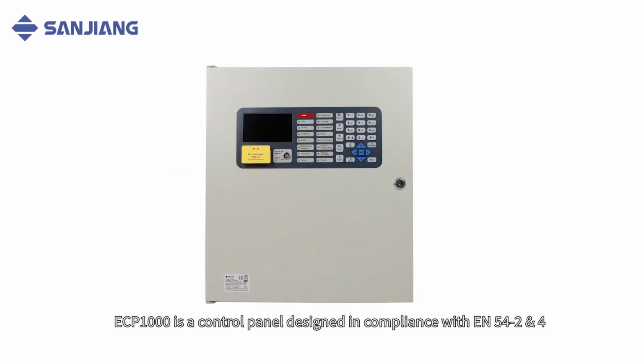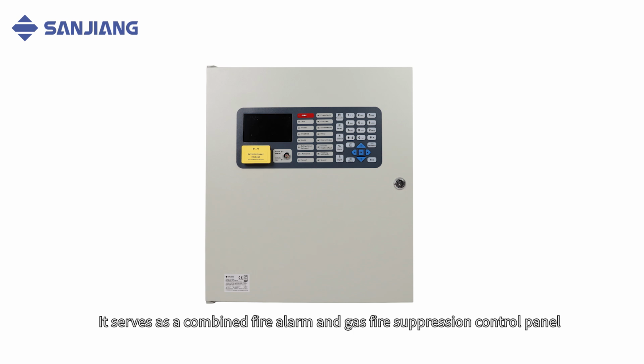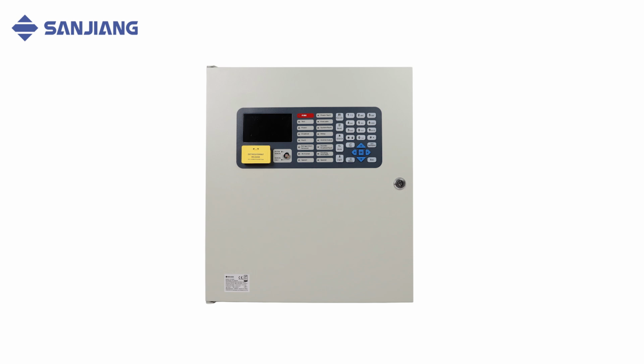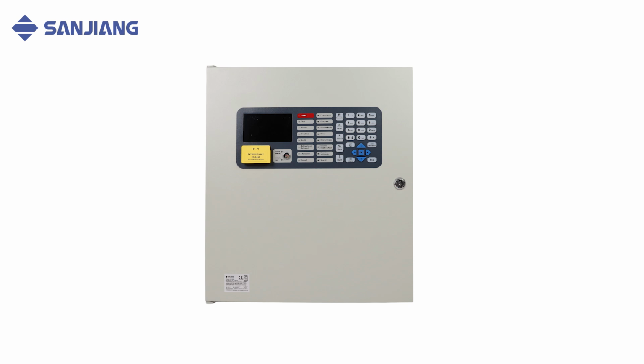ECP1000 is a control panel designed in compliance with EN 54-2 and 4, EN 12094-1 standards. It serves as a combined fire alarm and gas fire suppression control panel, utilizing a new generation high-speed microprocessor. It features a 4.3-inch color LCD screen for user interface, facilitating system maintenance with the capability to import or export system configuration files and historical data via USB drive.